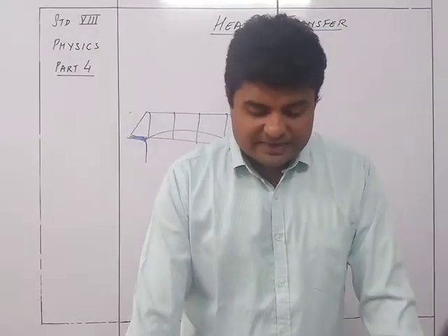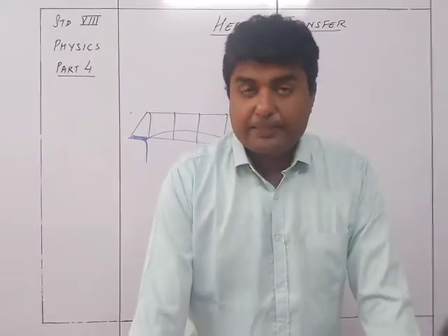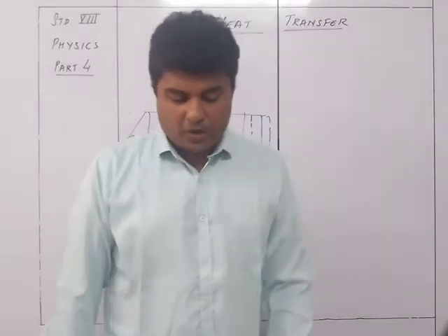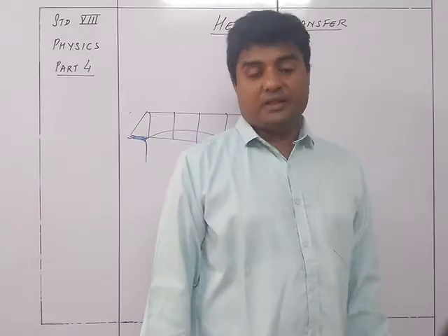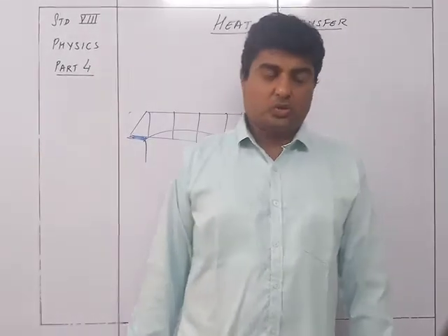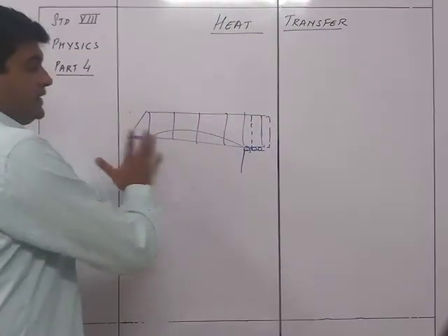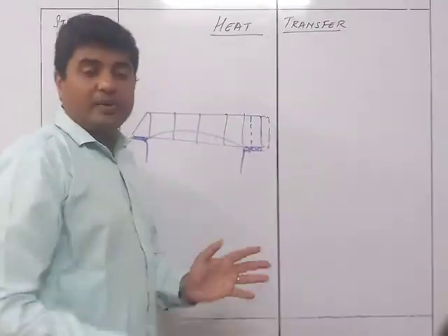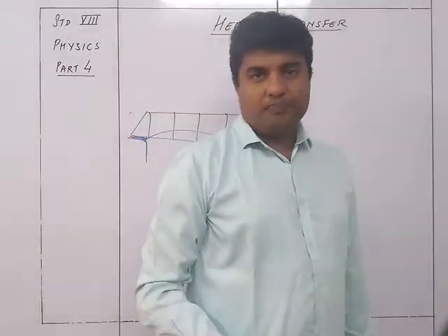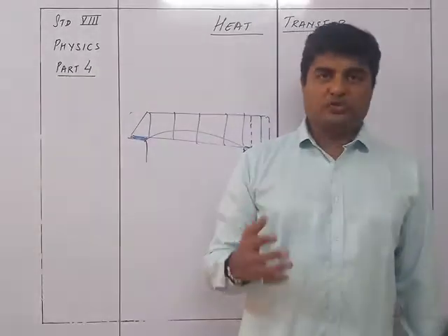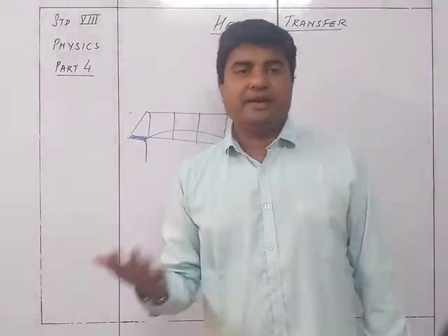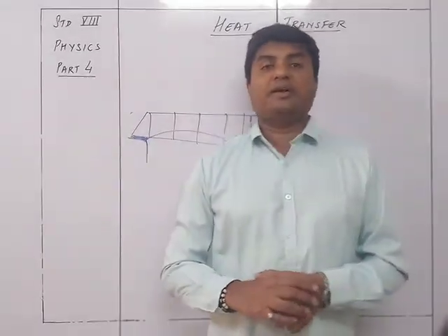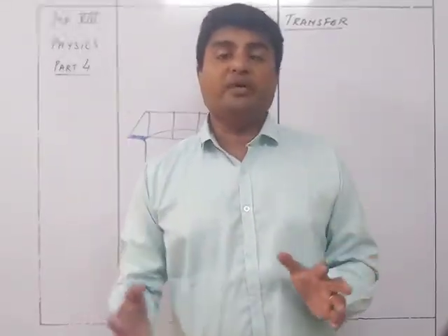So that if there is any rise or fall in temperature during summer or winter, girders may expand or contract without affecting the pillar and the bridge. So without affecting the pillar or the bridge, it can easily extend or contract without any kind of problem to the bridge. So the bridge will remain intact in any temperature conditions. Now this is much more important when the temperature difference between the summer and the winter is very high.